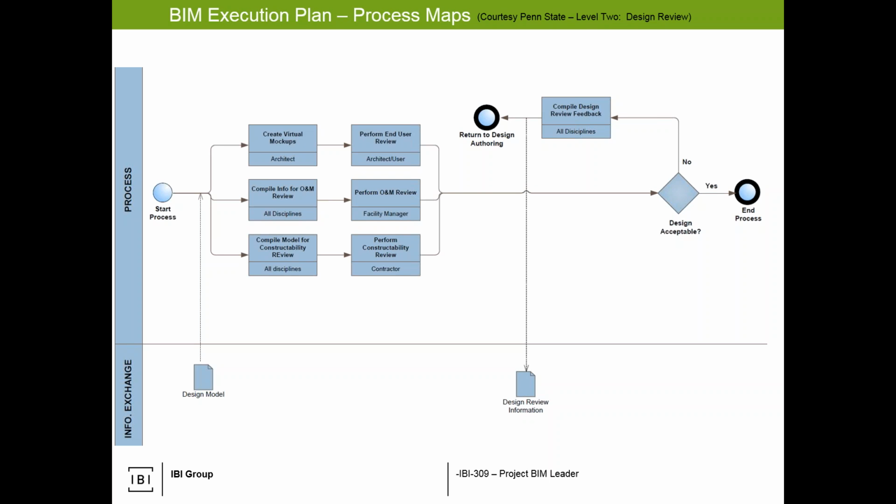And that's why, from an IBI perspective, we're looking to enhance these, and we'll have companion UK ones as well, to be used in conjunction with the BS 1192 standard. Design review, similar concept: start your process, grab a snapshot of the design model, and then you compile it, you review it for any operation and maintenance review, constructability review, perform your checks, repeat, deliver, etc.